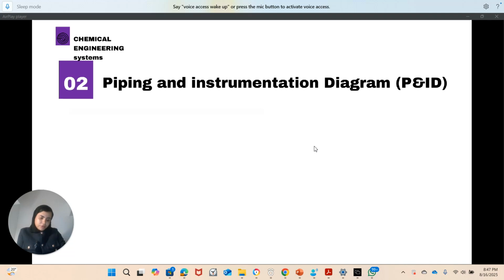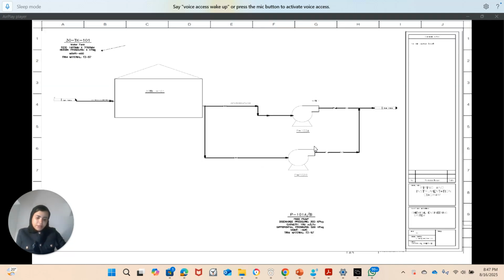And one thing I wanted to show you as well for the PFD is that if you are transferring or building the PFD from process simulation or HYSYS, in the process simulation and HYSYS you will have mixing points and split points.